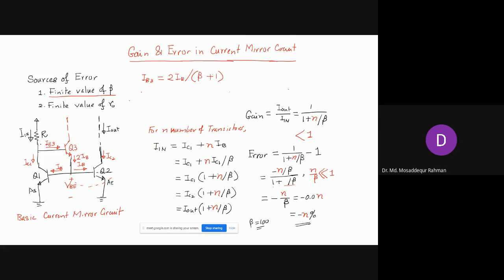So before, I in was supplying the full base current to IB. Now it is supplying only a fraction of this. Here it is supplying only the base current for Q3, which is only a fraction of what is needed. Most of the current is coming from here, which will be 2 IB times alpha, that's the IC, alpha IE.